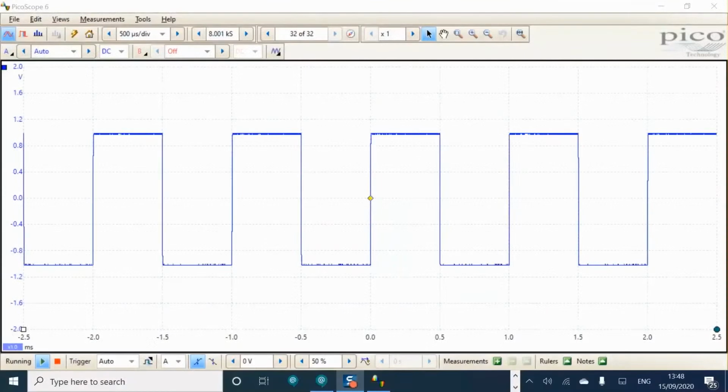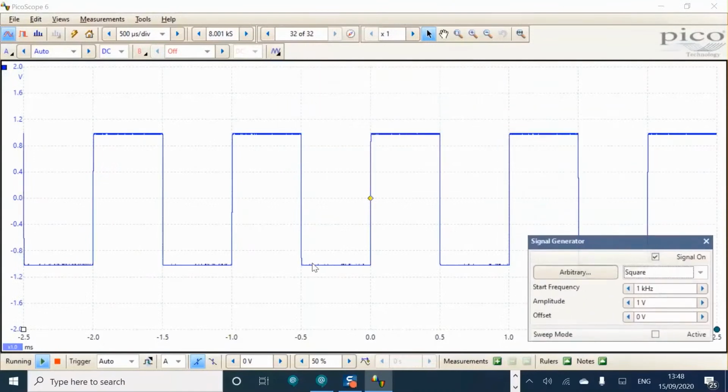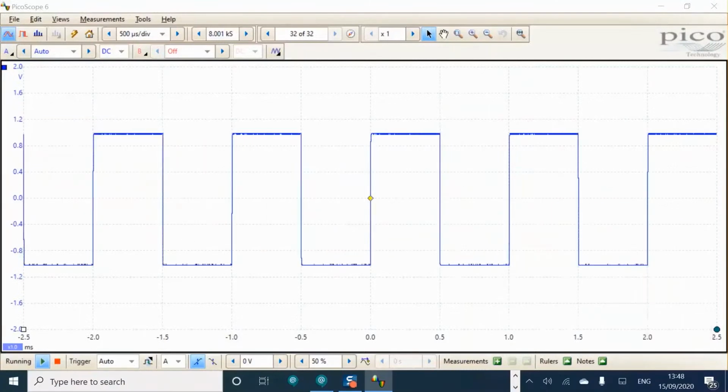The setup begins where part 1 ended, with a 1 kHz square wave displayed on channel A and the ×10 probe connected to the AWG using a BNC to crocodile clip cable. So let's open the generator menu and take a look at the various controls. If you find the menu covers part of the signal you're interested in, you can drag the menu to another part of the display, or even off the screen onto a second display to give you full visibility of the waveform.